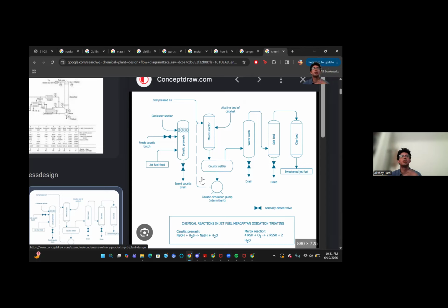So you're going to have heat exchangers. They're going to be like, okay, this reaction is going to give me this much heat that I can use to supply the heat to this distillation column. So I'm going to use a heat exchanger to get my flows into those units to be the temperatures that I need so that they react in the concentrations that I want.